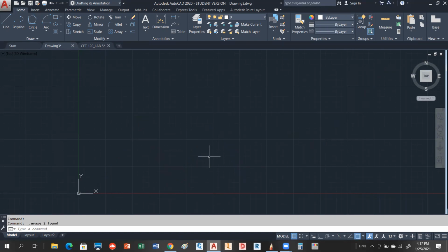So if you draw a polyline back to the starting point, it doesn't always necessarily make it closed, okay, which is kind of weird. Even though mathematically it might be closed, physically it might be closed, from the database standpoint, it doesn't think it's closed. So I'm going to show you the difference. And when you have width on, you can definitely tell the difference. So what I would like you to do is we're going to go into the polyline command, and we're going to start out at a coordinate like 2, 2.